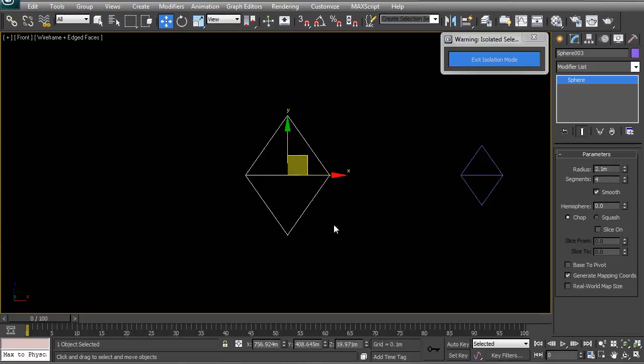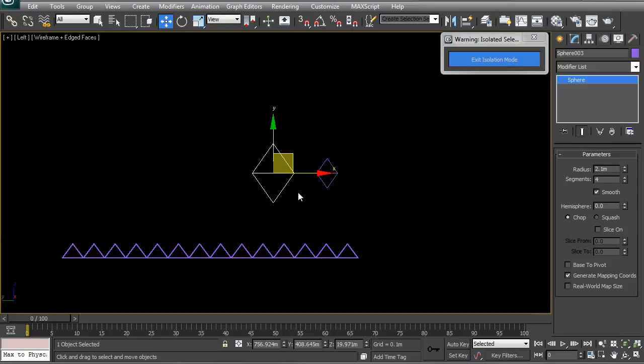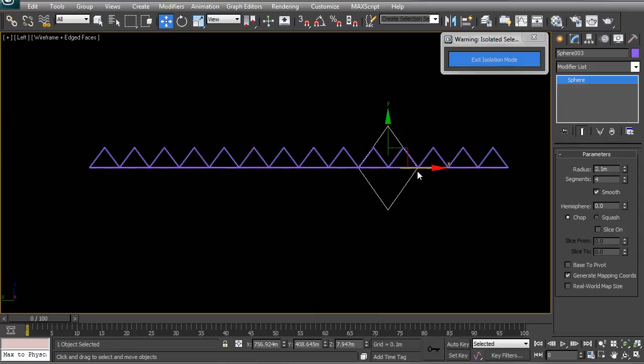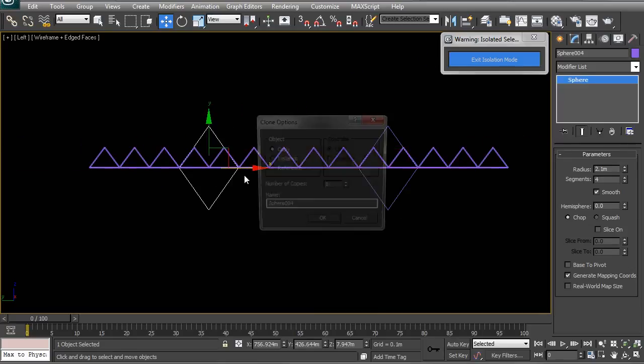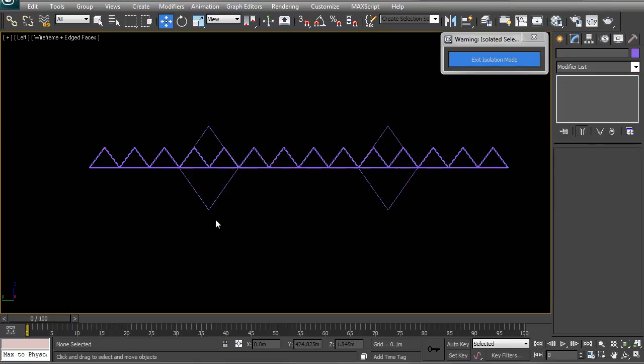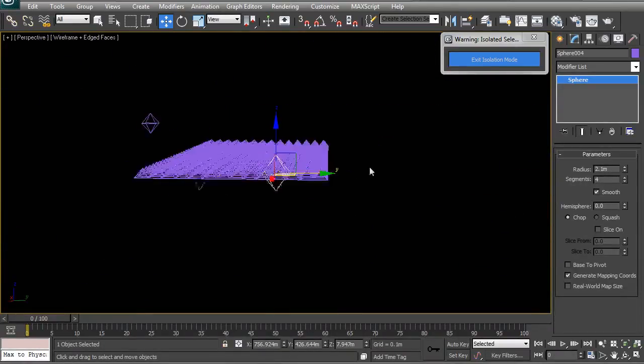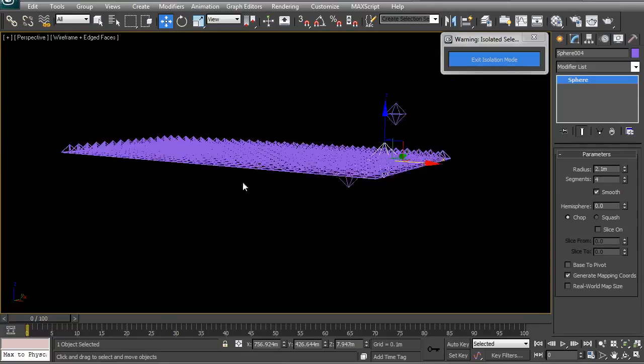And once we look in our left view, you'll be able to see that the structural decision about where to put them is not just aesthetic, it's also a question of how the space frame should be supported. So here what I'm going to have is 3 modules on either side and then 4 modules spanning, and then the set of 2x2s is going to be supported. So this is going to now occur in that direction, and it's also going to be repeated back.